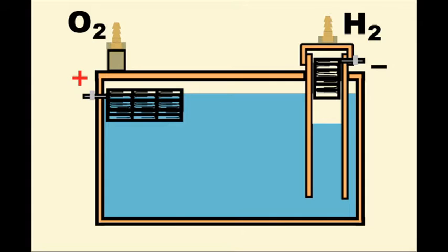The oxygen pressure being generated and held inside the oxygen chamber forces the hydrogen to come out at a higher pressure, since oxygen exerts pressure on the water, which forces the water up in the hydrogen production chamber pipe. This exerts a greater pressure on the hydrogen leaving the spout H2.